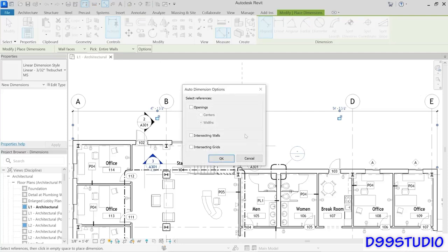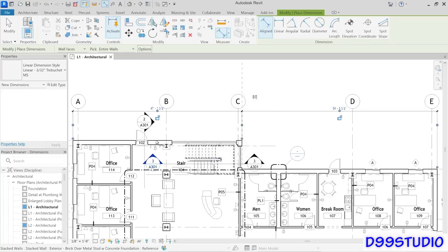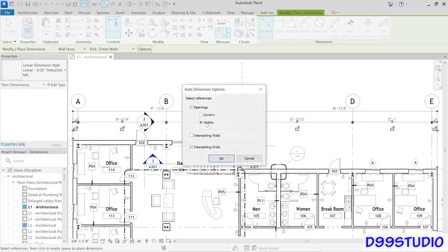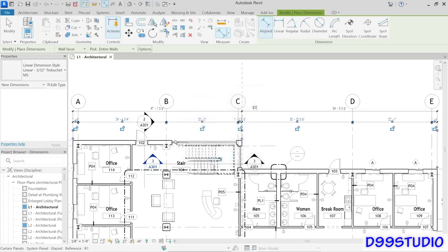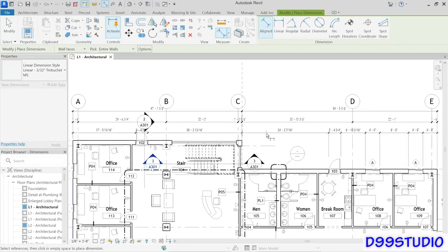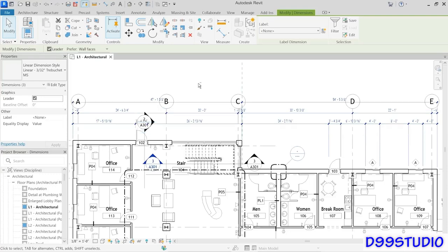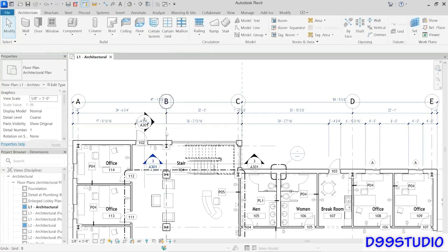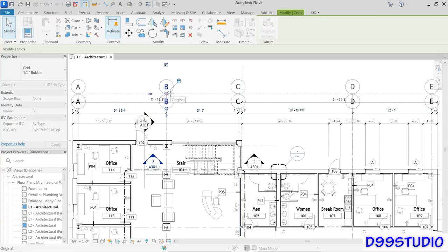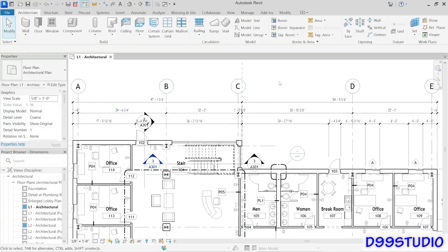So then you just start setting your additional options here. So we tab in for the first one, we click to select the second one, and then finally we do openings with widths without intersecting grids, tab in, select the second, and click to place it. If you want to fine tune the position of any of these, you can again use your nudge option. I think it's a good way to do this. And then of course we can adjust the column grids as required.